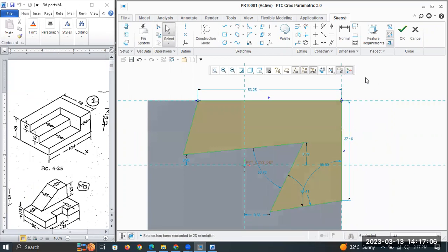Sketch view. Now, this is my rough sketch, which consists of 6 lines. Now I should make use of these constraints. This should be vertical. This should be vertical. This should be horizontal, and this should be horizontal. But still, I can use equal. This step depth is equal to this one, and again this step depth is equal to this one. You can see L2, L1 differences. Come out of the command, only two dimensions are there for 6 lines.